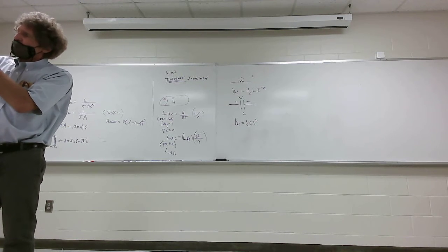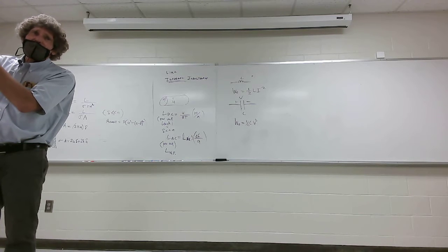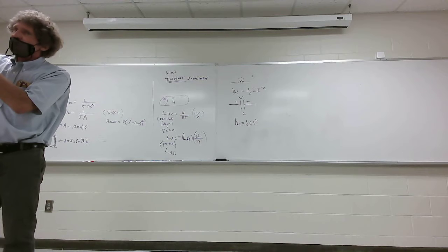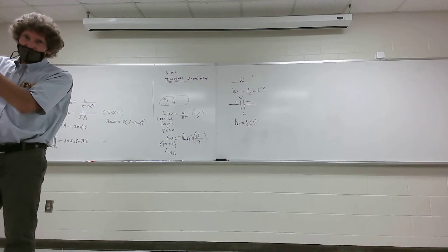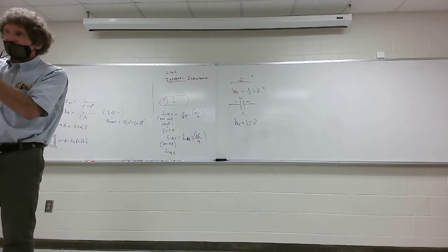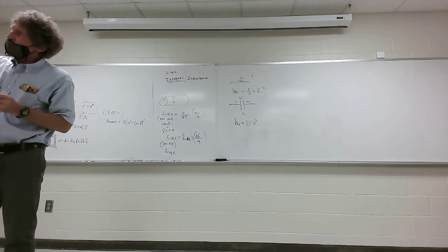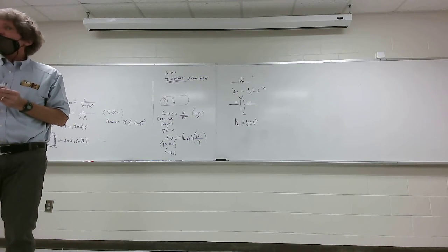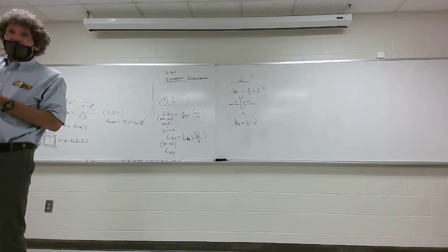So if you have 2 wires that are separated by nanometers, all the energy is internal to the wires because there's no real area for the fields to expand. You all follow me? The fields are basically 0 outside of those 2 conductors because they're almost on top of each other. If you have a coaxial cable, you have an inner conductor and an outer conductor, where the outer conductor's current is exactly equal to, but in the opposite direction, there is no magnetic field theoretically outside there.